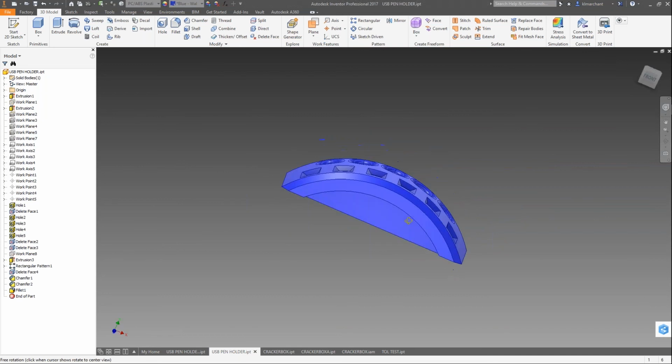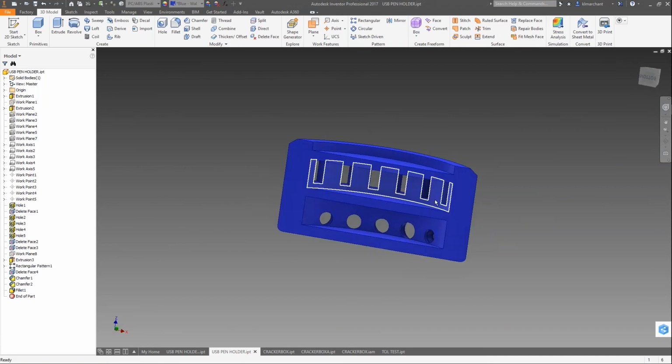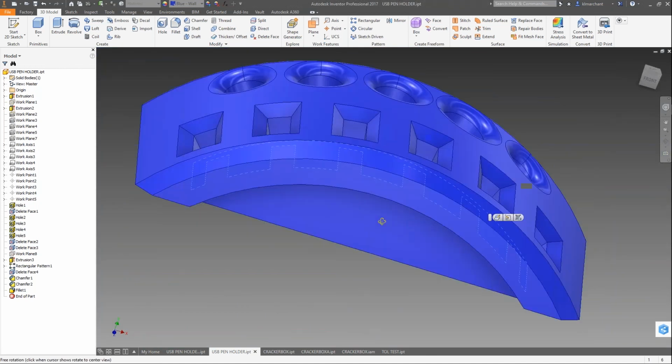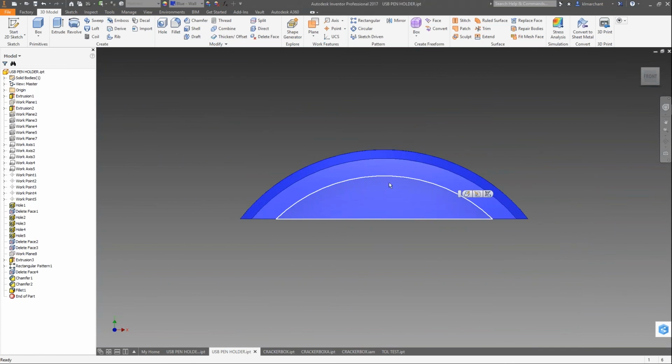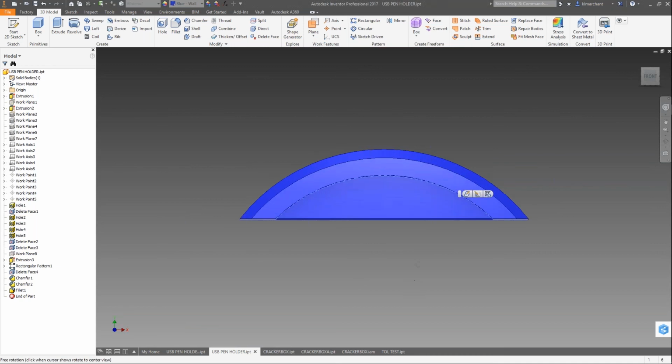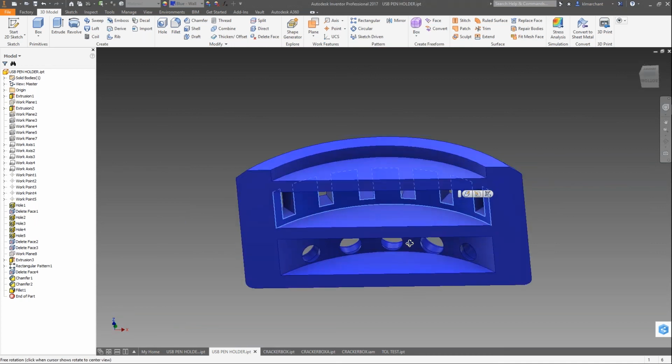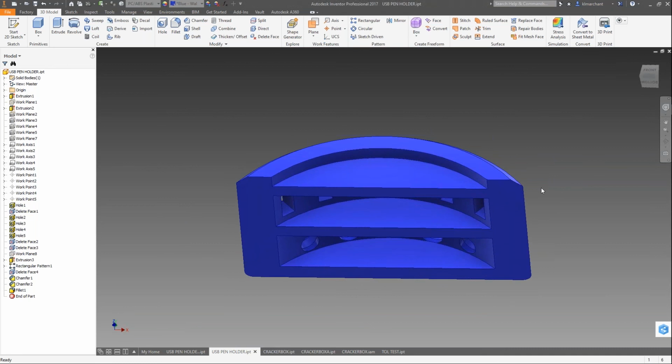I thought to myself, how can I get the same number of items in here to clean up my surface, but have a successful print? What I decided on was an arc, so it fans everything out. This particular radius that I used, if we look at it, we can see it follows that arc, was such that I did not need to print with support material.